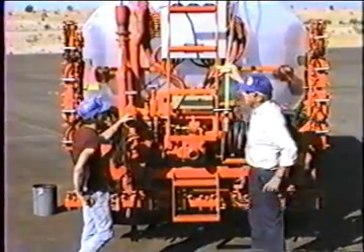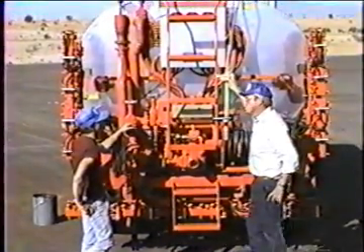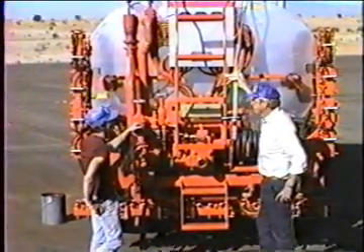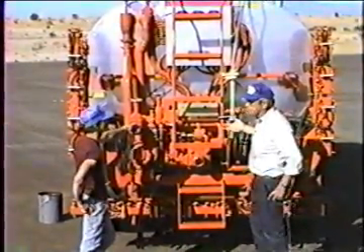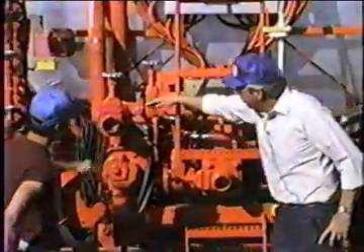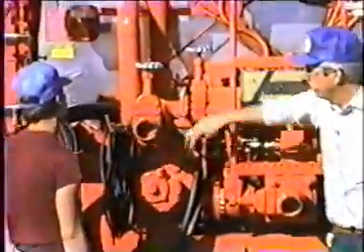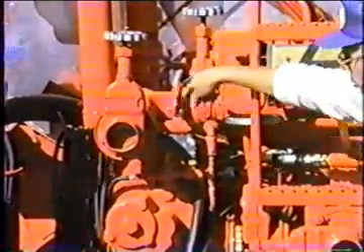If you're going to do hand work, as you get out of the cab of the truck, pumping forward, set it on about 60 gallons a minute. When you come back here, the spray bar is circulating because we've been spreading. Everything is just circulating here, 60 gallons a minute. Right here is a ball valve on top of the pump, and it's labeled hand spray. Open that ball valve.